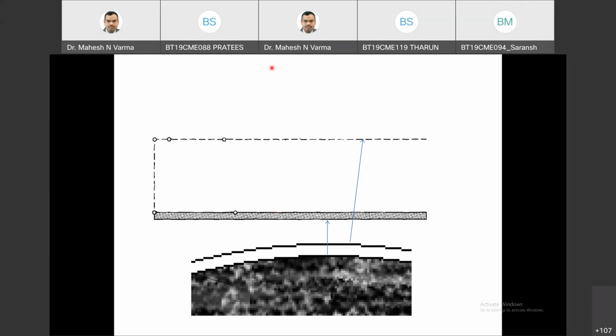What is happening? Here the bulk of the fluid is there. From here A is coming in and diffusing. Here there is no resistance to mass transfer; it is freely moving. The overall resistance to mass transfer is in this film only. So A is moving in by molecular transport and convective transport, reaching this surface and reacting.